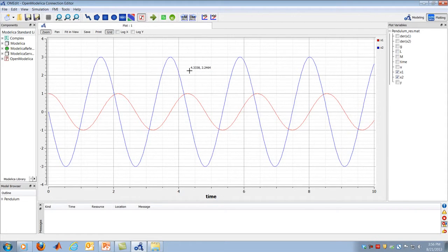We will find out later in the class that, very approximately, if you linearize a pendulum model around small angles, which the initial condition for this pendulum is not a small angle, but if you were to approximate the pendulum as having small angle initial conditions, the natural frequency of the pendulum is the square root of g/L, and so the position will equal initial position multiplied by cosine of the square root of g/L times time, the natural frequency, the square root of g/L, in radians per second.